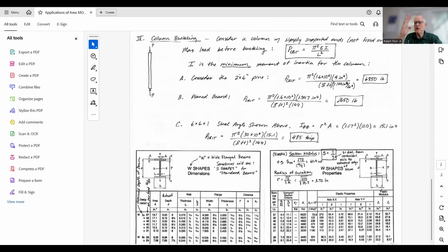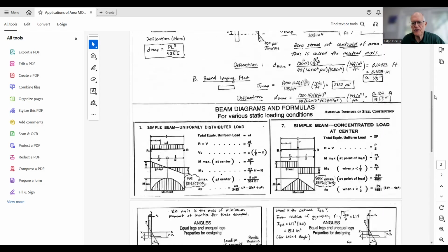So if you turn this beam on its side and load it like a beam that way, you would be concerned with the area moment of inertia about that axis. If it's in its normal orientation with a flange at the top and the bottom, then you're interested in the area moment of inertia about the XX axis, and that's here in the table. You'll use those numbers a lot in mechanics of materials.